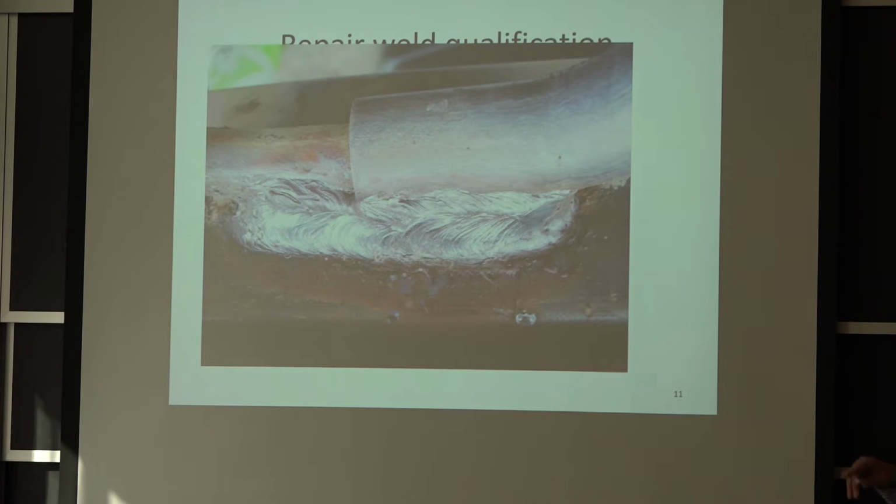So there was a slag on it, and what happens in this case is when you're done with the welding, you have to break down that slag. It's a little bit like a piece of glass that's dark and over the weld, and then you expose this. And on a process done by hand, a lot of times it's slower with that electrode, and that's why you see these striations of the welding.